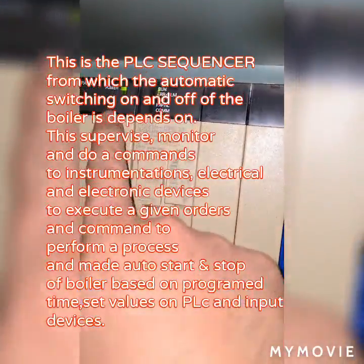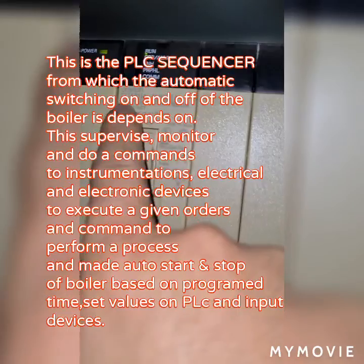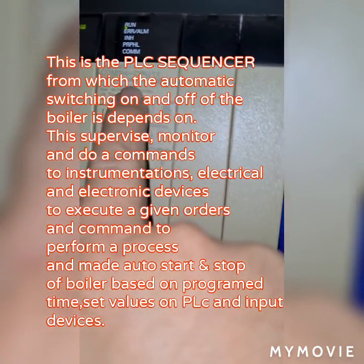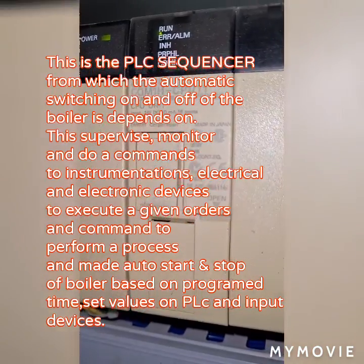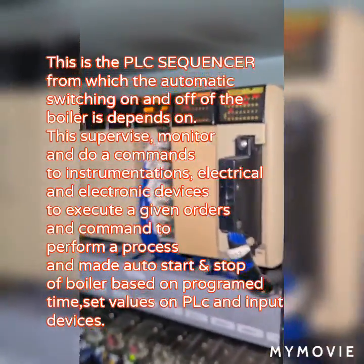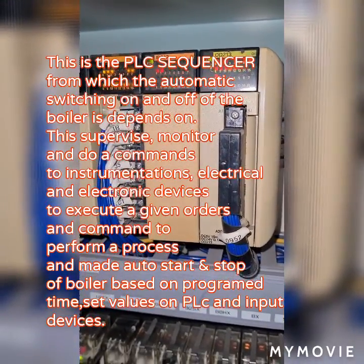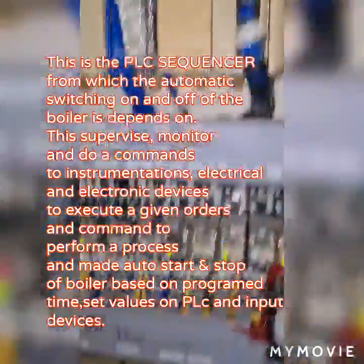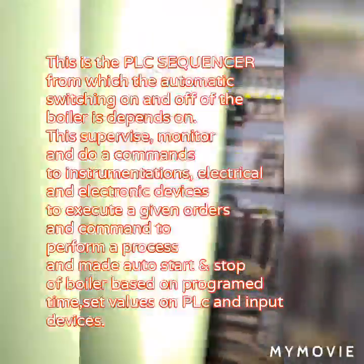And here you can find the programmable logic sequencer, from which the automatic switching on and off of the boiler depends. It supervises, monitors, and gives commands to instrumentation, electrical, and electronic devices to execute given orders and perform a process, making the boiler auto start and stop based on program time set values on PLC inputs and devices. As you can see, this PLC sequencer has a big role in auto starting and auto stopping of the boiler.